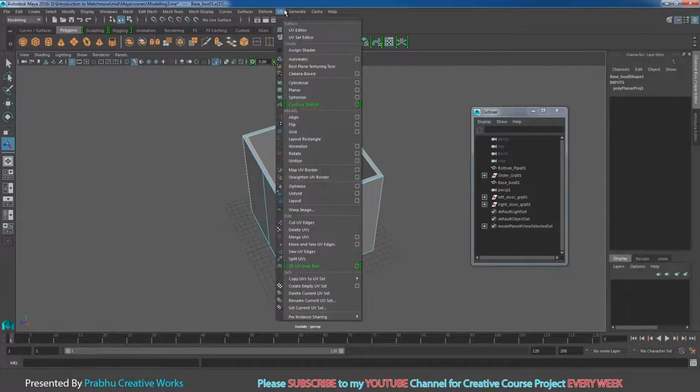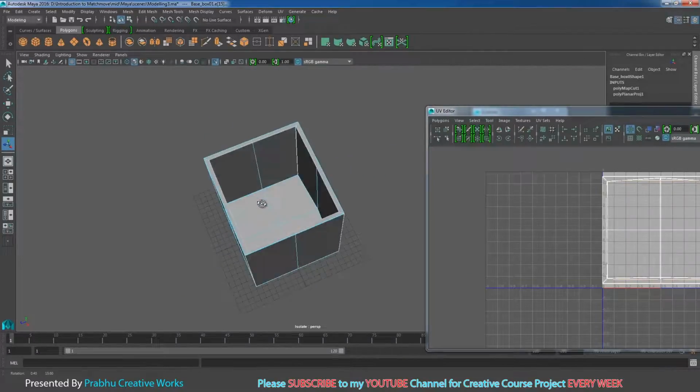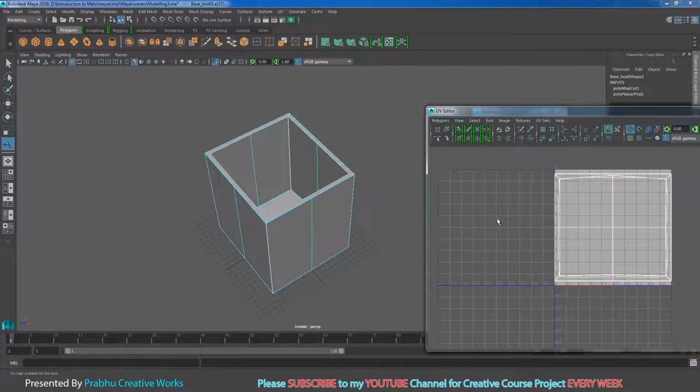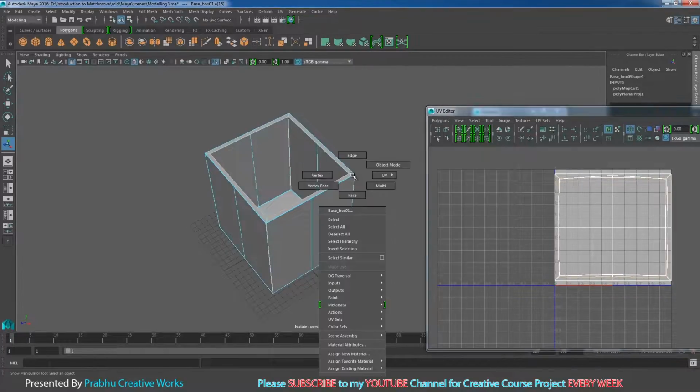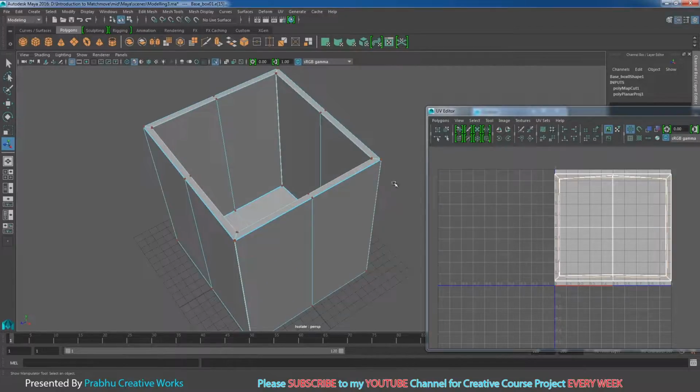Now go to UV and choose UV Editor. Here you want to choose separate the UV along the selected edge over here, which means all the selected edges will be split. Now right click in perspective, right click and choose UV. Select any UV on the outside, don't select inside.